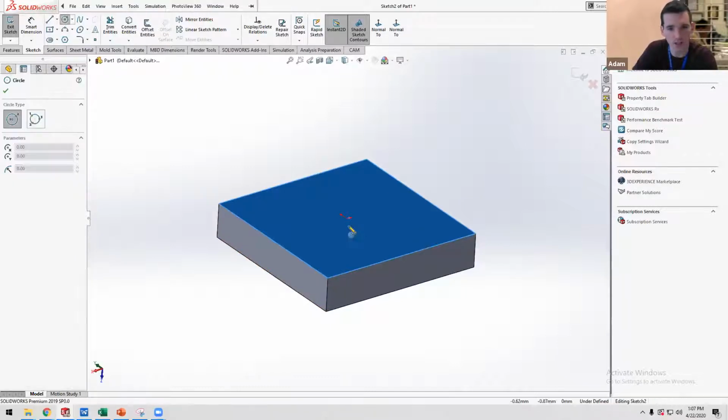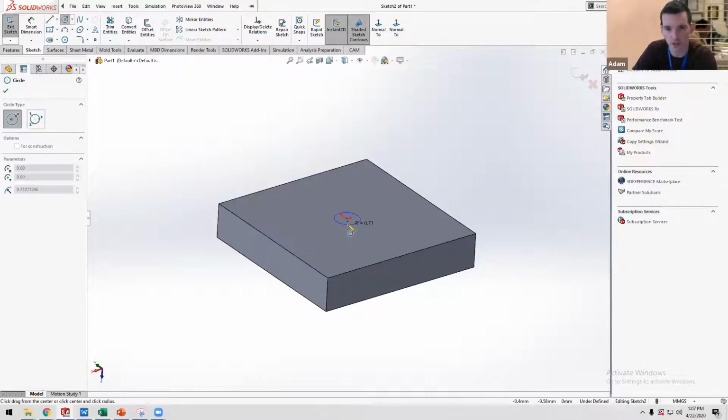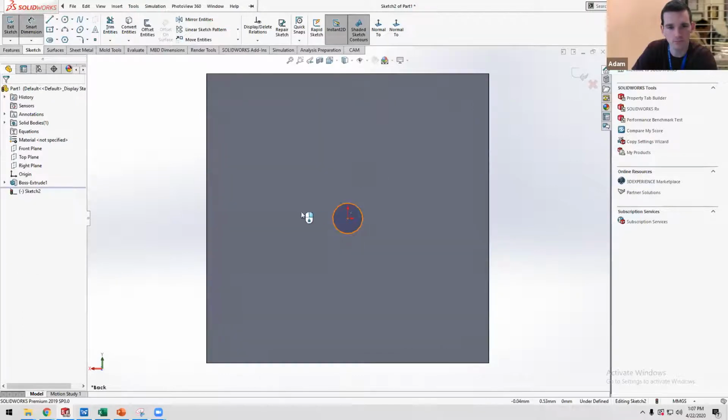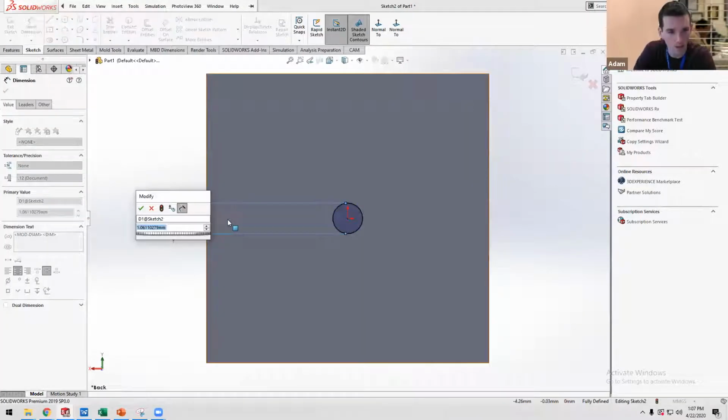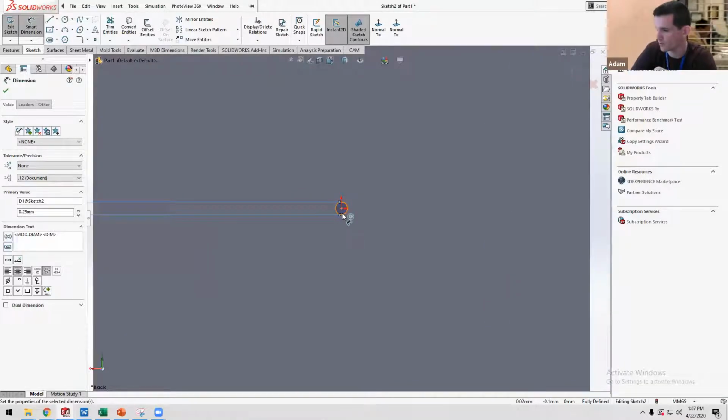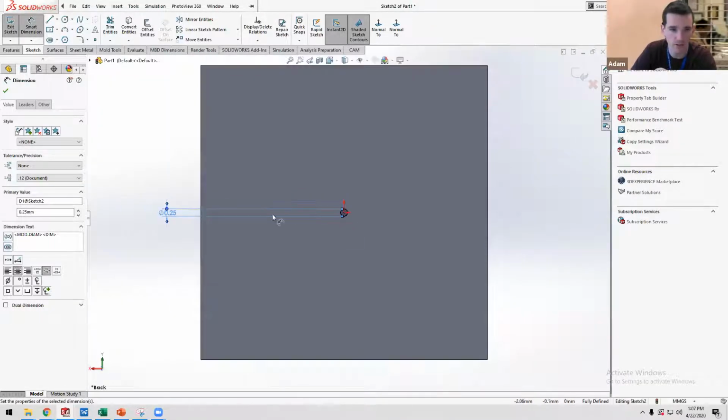And I'm going to make the base of my microneedle, which will be a circle. So I'm going to make a little cone. And I'm going to make this sort of at the limit of the sizes that are capable with the Formlabs printers. So you have a rough idea, if you were making a model with very small features, what is the minimum size I could get away with for that SLA printing? So 1/4 of a millimeter is the smallest small feature I can make for microneedles.